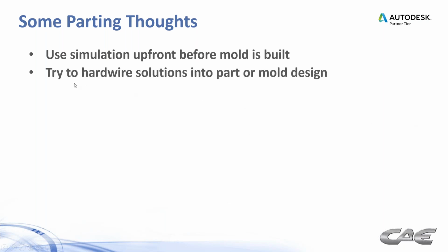I'm a big fan of hardwiring solutions into the part and mold design. If you have to go back and figure out the process that's going to fix all your ills, you're asking for trouble again. A big processing window is where we want to start, and that starts with good part design and good mold design.